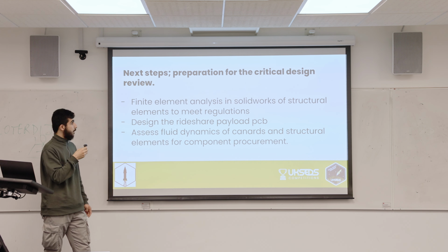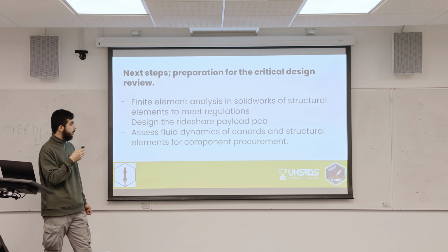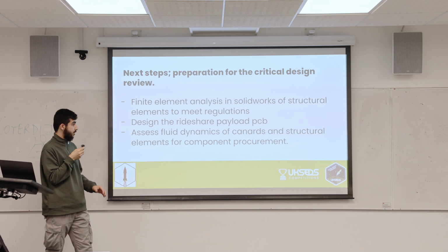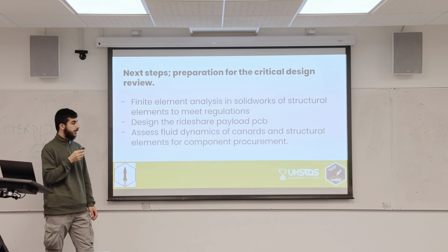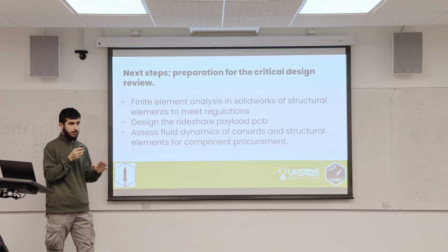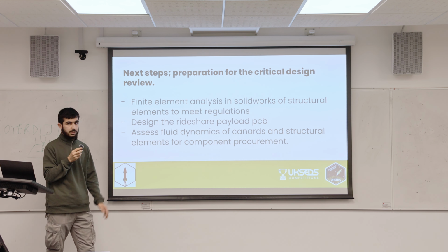For the next steps, preparation for the critical design review. We are going to be doing a finite element analysis in SolidWorks, and to meet regulations, to see if the components handle the stress. Because we will be implementing Q-learning, we need to find a processor and PCB that would be appropriate. And we will be assessing fluid dynamics of canards and structural elements to find the torque required, and to buy the right servo.